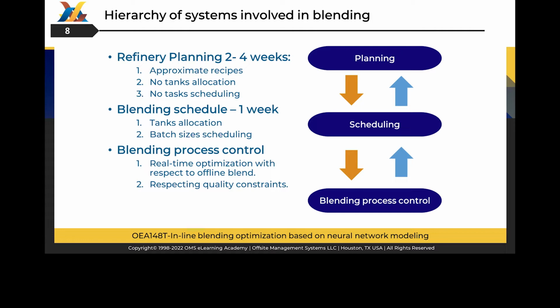The blending optimization must consider the broad scope of the refinery's operations. At the highest levels, the refinery operations planning takes place, driven by the market demand for certain products and raw materials prices. These market constraints and the refining process model should dictate how many products the refinery should produce over a particular horizon of between 2 weeks and 4 months. We are considering allocating specific storage utilities and shipments to schedule at this stage.